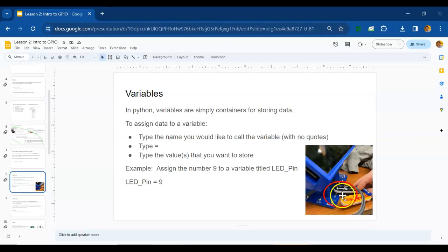But if you look, that LED circuit is connected to pin 9. And that's what we were using for the LED circuit project. If we don't want to have to remember it, because once we plug this in it covers up that number, then all we have to do is give it a name up front, and then we can refer to it by that name every time we use it in the project. So instead of using a 9 every time, we just use LED pin. And then we can forget about it.